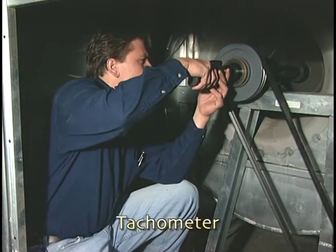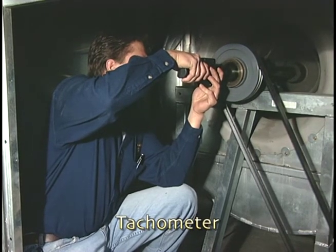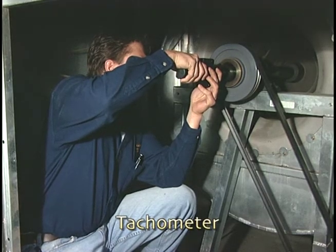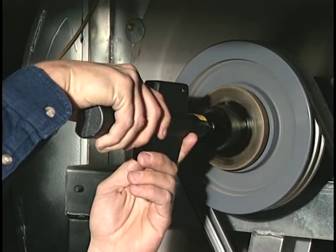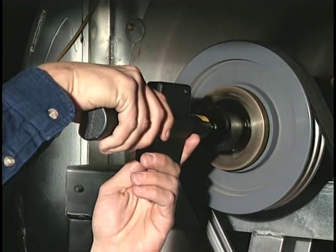This is a handheld contact tachometer. Contact tachometers are used for measuring rotational speed when the shaft of the tested item is accessible. They are usually supplied with several rubber or metal tips for centering the instrument on the rotating shaft and to ensure proper contact without slippage.